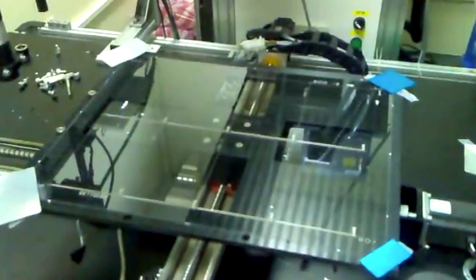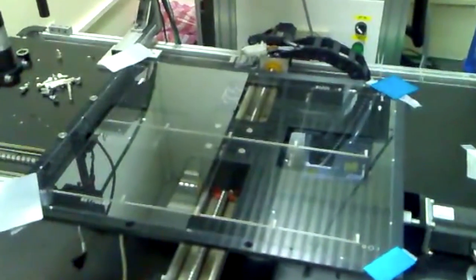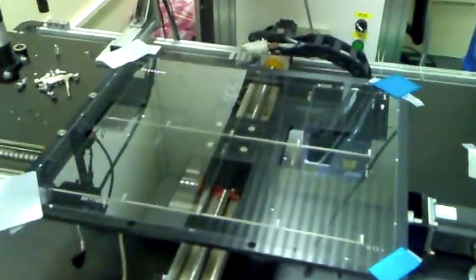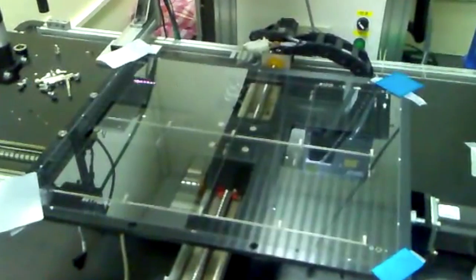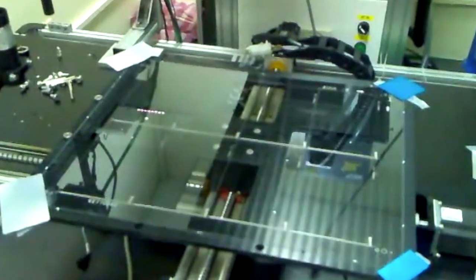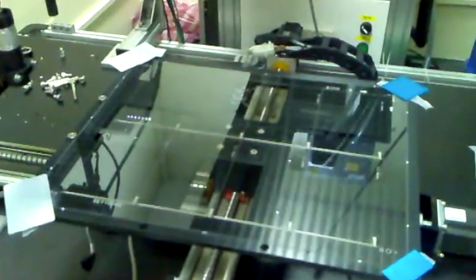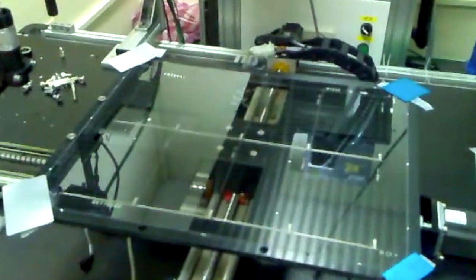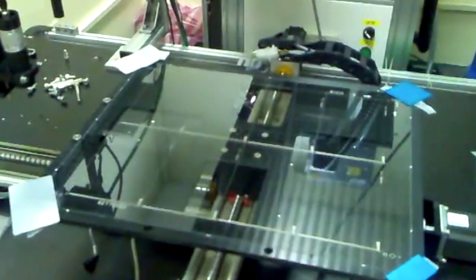Laser lithography is an etching or scribing technique which uses a laser to remove a thin film layer from the surface of a material. This process is used to remove the deposited layer of I.T.O. on a material in order to create a functional circuit, using the remaining conductive oxide to guide electrical signals.